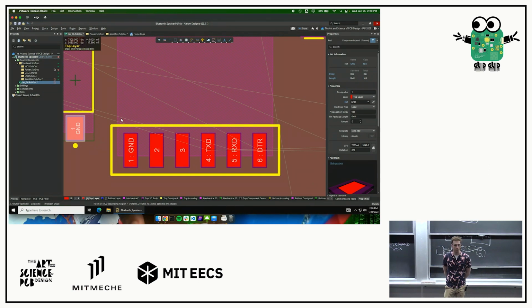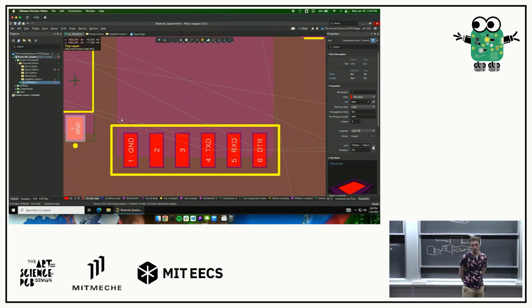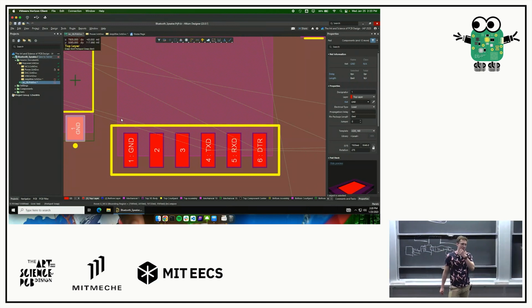factor. I usually go with at minimum a 1.5 times safety factor, if not a 2 times or higher safety factor. And for really high current stuff, I'm sitting there with like an 8 times safety factor because you really don't want it to fail. So that's another thing, I don't know if we've mentioned safety factors at all. Yeah. And that concept also applies to everything we design, right? So especially when you're picking